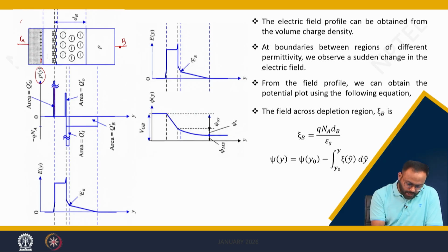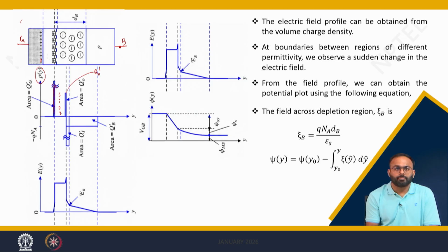So the charge will exactly appear across the metal and silicon dioxide interface. This positive charge is very, very high, and hence we show it by some discontinuities. There is also positive charge present at the oxide, which we term Q naught dash. This positive charge is fixed and depends on the particular fabrication process. Because of these two positive charges, there is negative charge coming in at the surface in depletion and inversion condition.